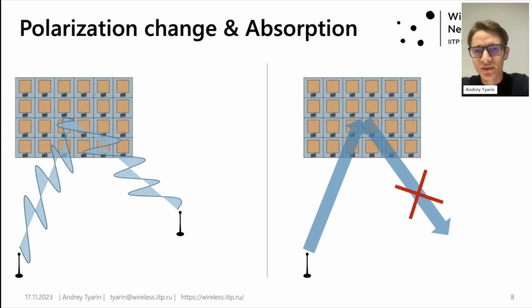This was realized due to anisotropic properties of the UC, which made a phase shift in the horizontal component of the wave, but none in the vertical one. However, to switch from linear polarization to circular and otherwise, the unit cell itself has to be divided into separate elements, and these elements' impedances need to be tuned independently.